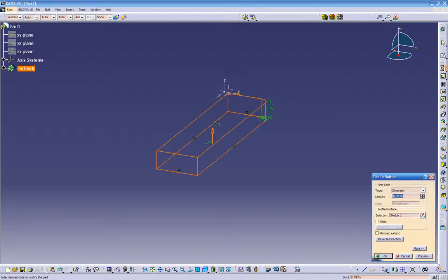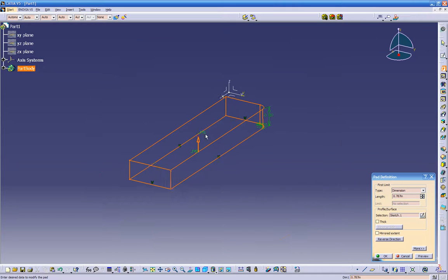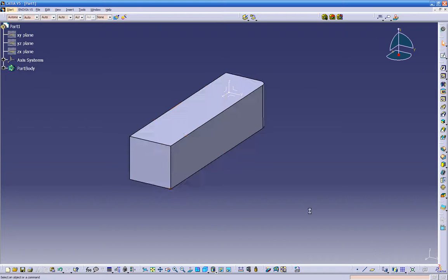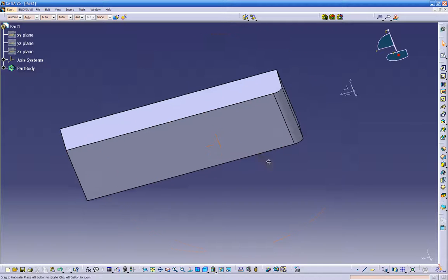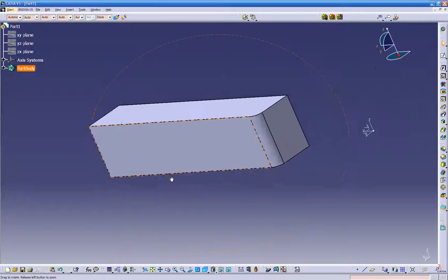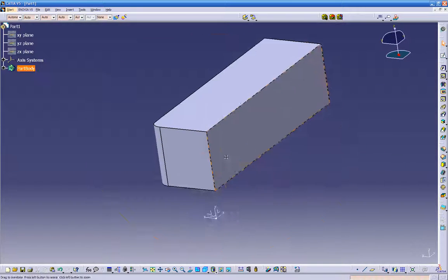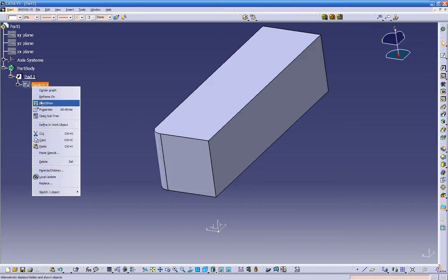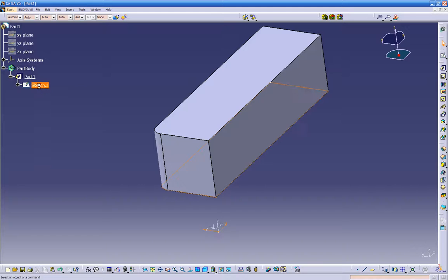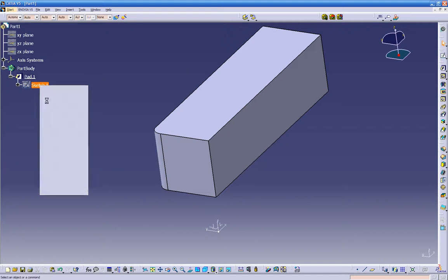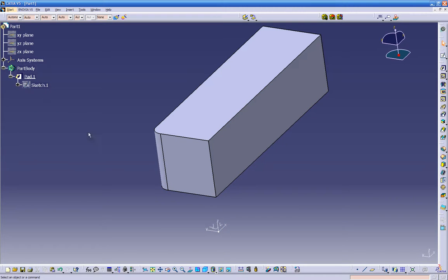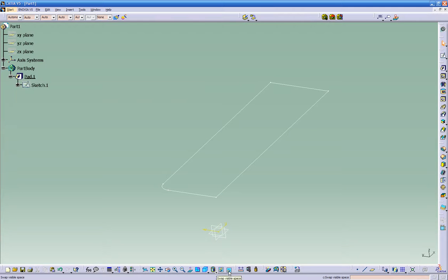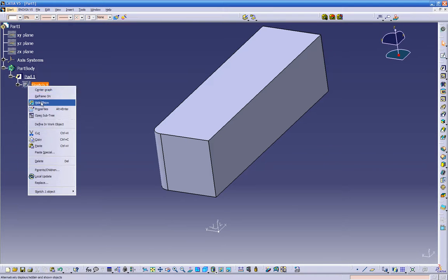create a pad, we can click on the limit, move it up and down, click OK. We can add fillets to the pad on the 3D mode view. So we can create on the sketch view, see over here on the sketch, if you do right click and turn it on, so you can turn it off, turn it on. What it does, it just puts it on a no show level, which is up here. Okay, so we can bring it up again.